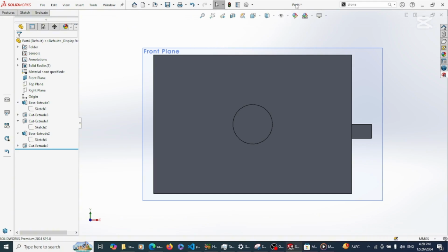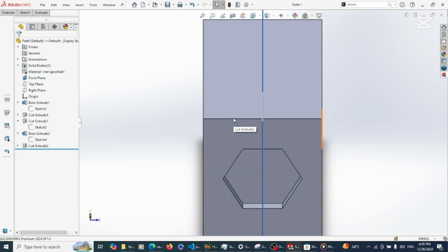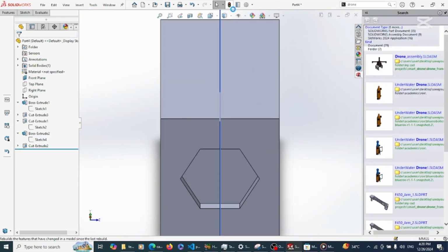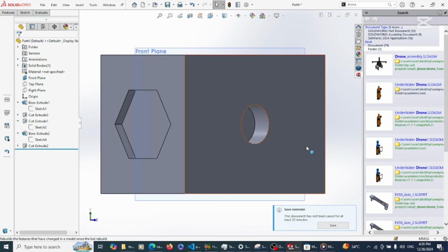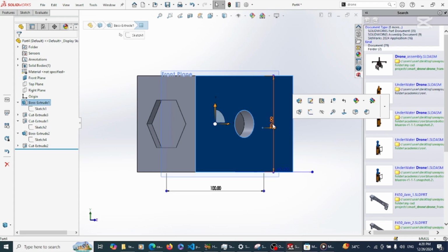Okay, it is saving. The name should change soon. Showing part 1, but the name should change soon. So now, SolidWorks will update later. So let me try and review it. This symbol here, rebuild, it means rebuild. What that does is, for example, I click on this face, yes. So I'm saying that the height I gave this is what? 70. That's the height of the sketch.